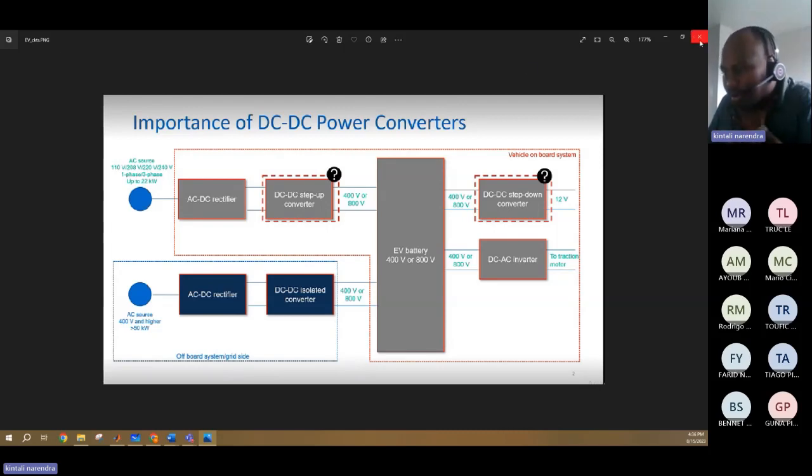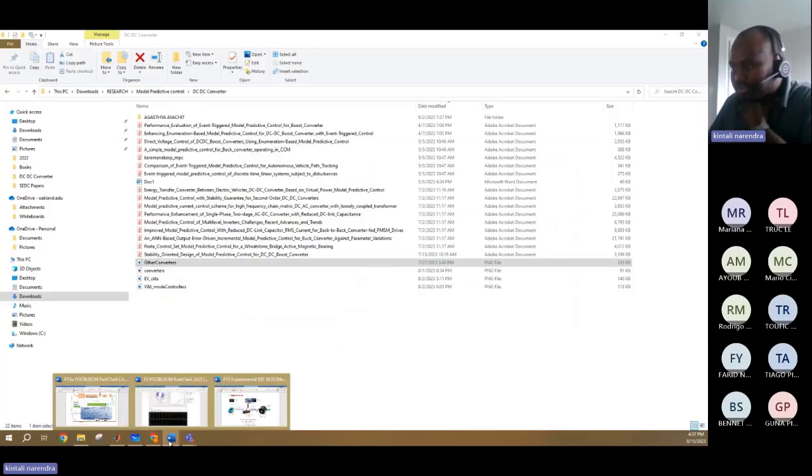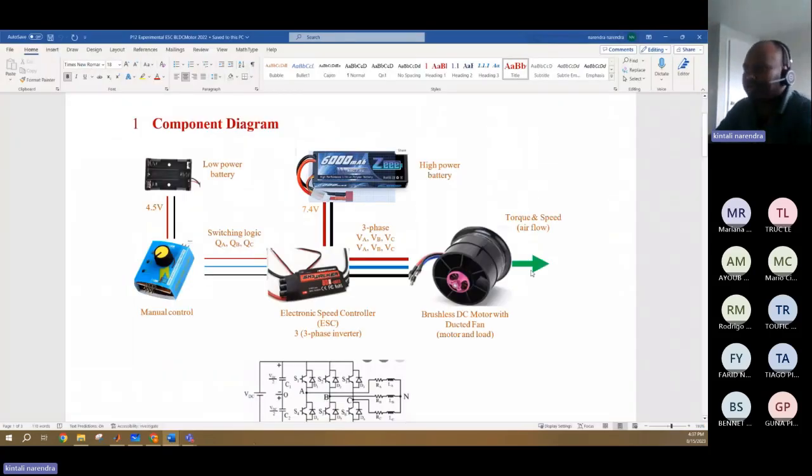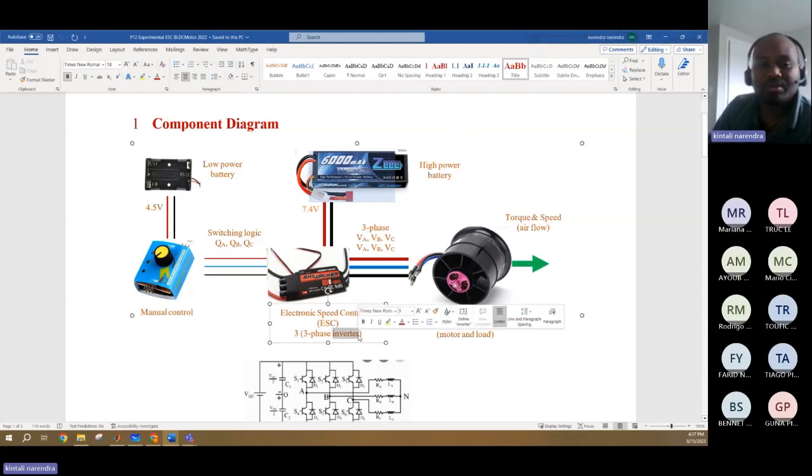That is your question. Now coming back to our topic of brushless DC motor. This is an example of a brushless DC motor. In a permanent magnet synchronous motor, I take AC power supply directly, whereas in a brushless DC motor, I take a DC power supply and, using an inverter, convert it into three voltages, VA, VB, and VC, and provide it to my motor.